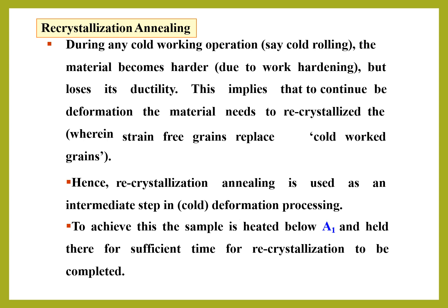Next one is recrystallization annealing. Normally, when this annealing is done, it is for any cold working process, after which the material becomes very hard. Because of this hardness, it will lose its ductility, so we have to improve the ductility. Again, we have to do the recrystallization annealing.